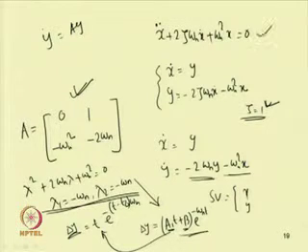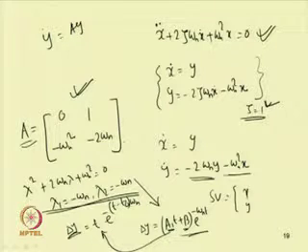Here we have taken a simple second order differential equation and converted it to a set of first order differential equations, and by perturbing it we can obtain the Jacobian matrix. Putting the determinant of A minus lambda I equal to 0, where lambda is the eigenvalue of the system, we can get the solution, and if we have repeated roots, the solution will be of this form. If this perturbation grows, then the system will be unstable, otherwise it will be stable.